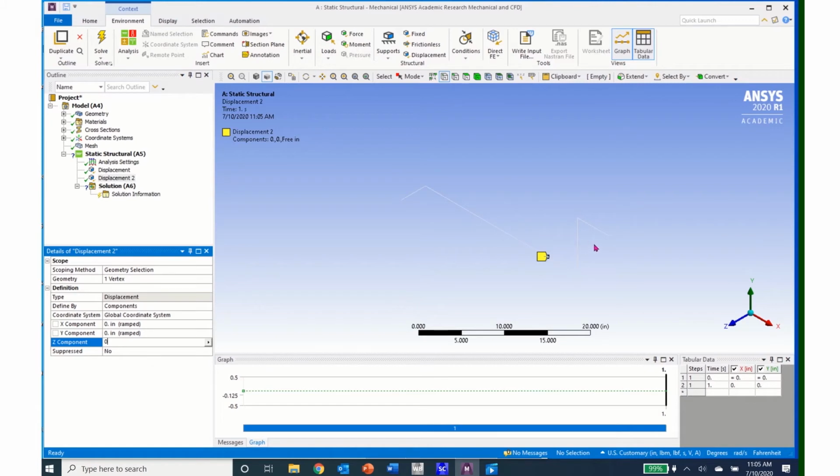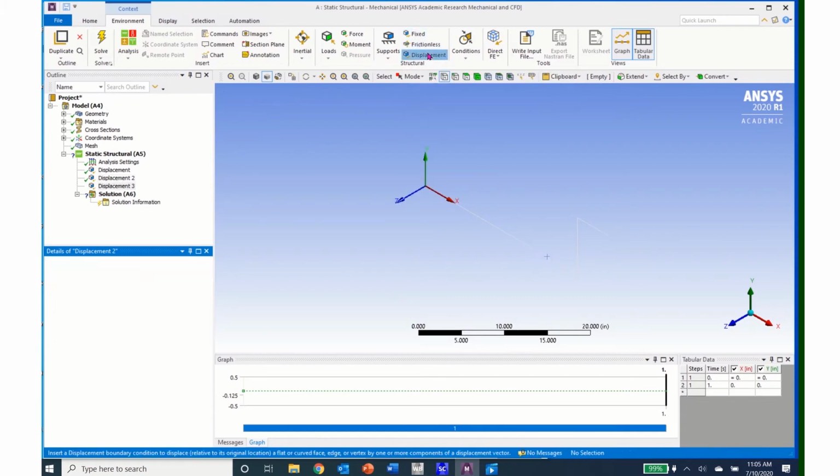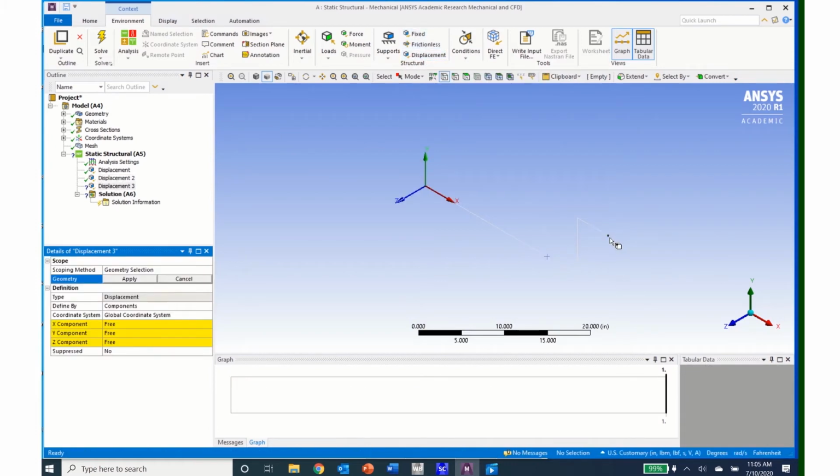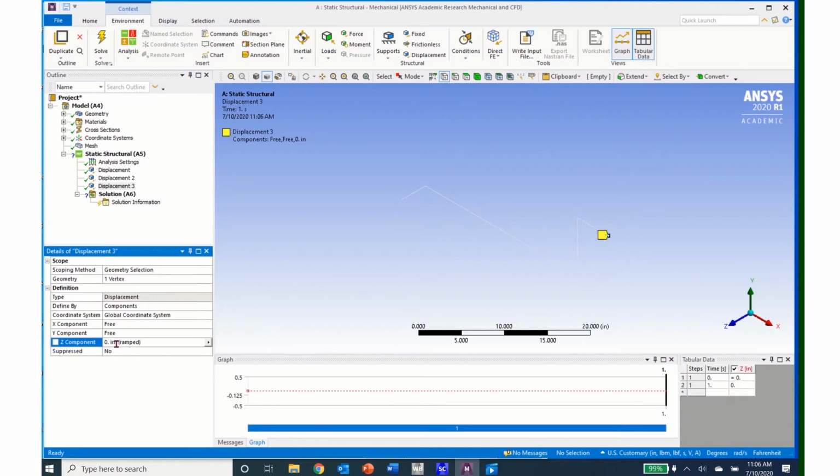I have one more displacement boundary condition that I will apply. It's up at the handle, so I will click on the displacement boundary condition, come over and select the handle vertex, come over and click Apply, and this I will only fix in the Z direction. And this Z direction boundary condition is to resist the vertical load out here on the end of the beam that is causing this whole system to twist. So a Z boundary condition here will let me determine the reaction load that will hold the system in equilibrium. So I'll click a 0 for the Z boundary condition and then click Enter.